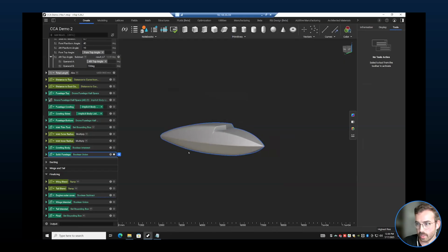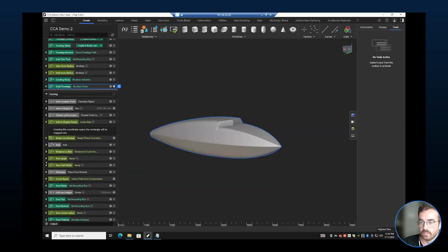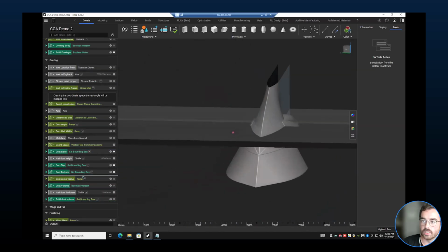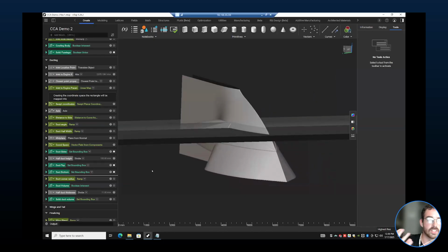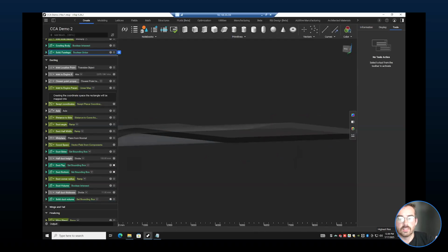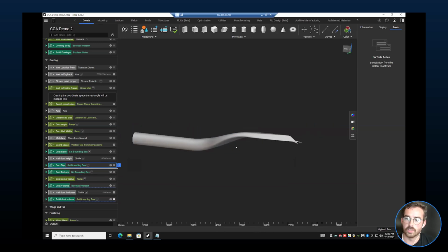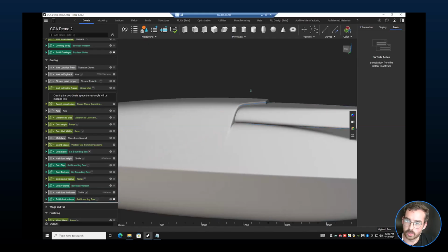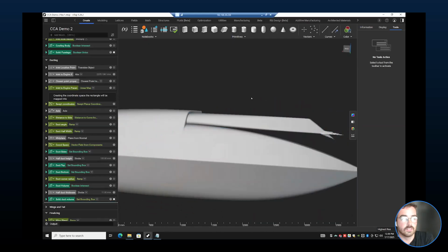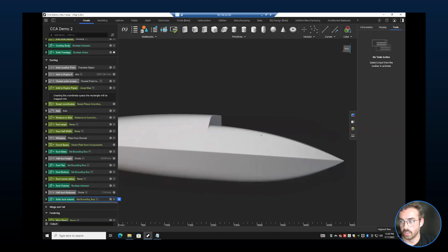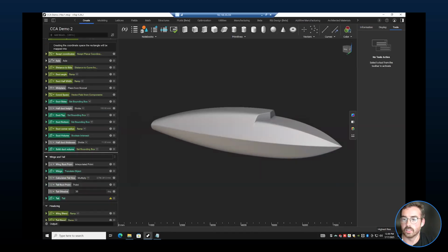So if I go back over here and say, okay, we have our fuselage, and now what we care about is the ducting, right? You can see that the same thing is being applied over here. So I have these infinite spaces, and I'm just saying the thing I care about is the intersection of all these spaces. Now, again, this might seem a little bit weird, but if you think about it, you can usually relate these things back to design drivers. So in this example, I care about the fuselage, and then I want the fuselage to meet the top of the duct in a nice way, and then I want to trim that later. And actually, this body is really useful because I can use this in CFD later, or I can use it to compute area ruling, all of that. So these end up giving you reusable tools for later on.